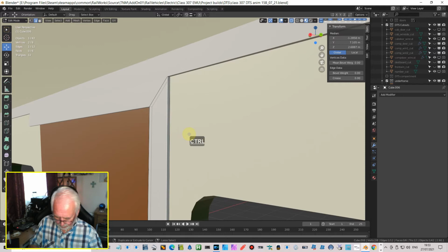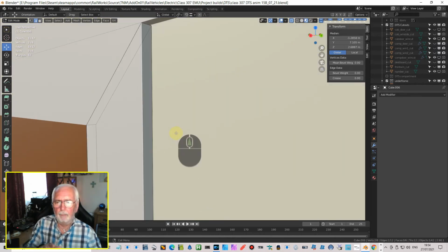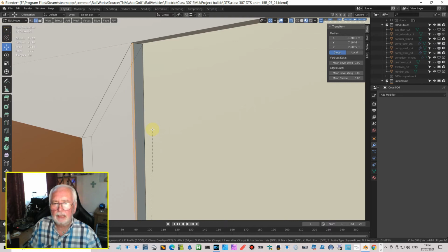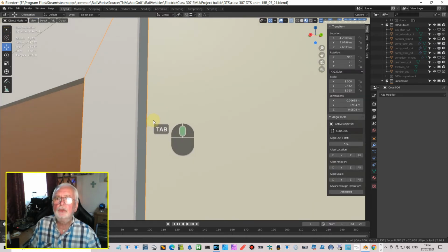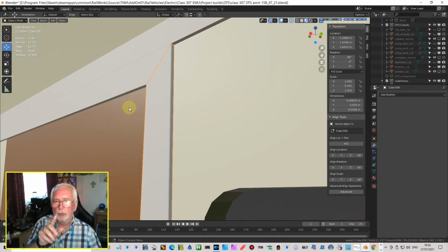There we go. Now if I go to bevel this, there we go, a bevel, okay, and pull it apart a bit. It's already gone to 16 edges now. So if I add more segments to the bevel, you will see the triangle count goes up. Okay, now we don't really want to do that. So to get around that, one segment should do it. So for instance, we go and do it again, then just that one segment should be enough to give the illusion of a bit of curvature at the edge of our cubes. So that's what you want to do, put a bit of bevel on.